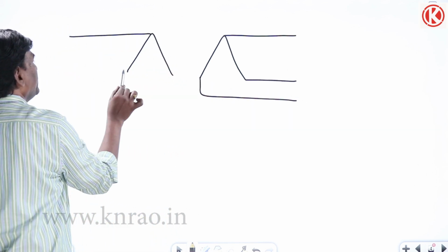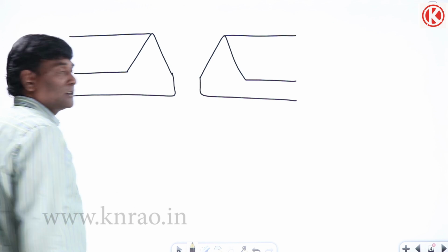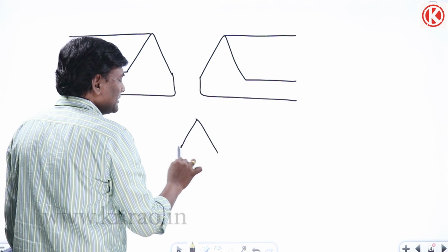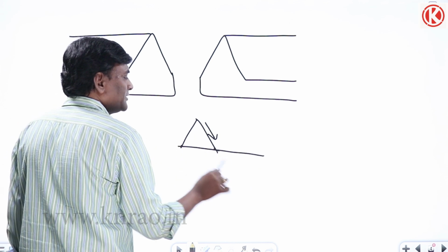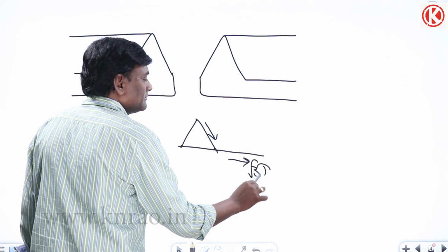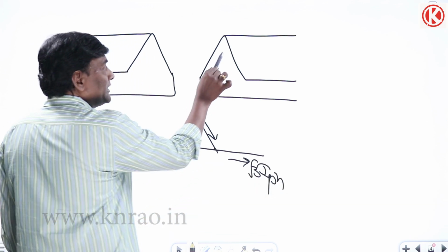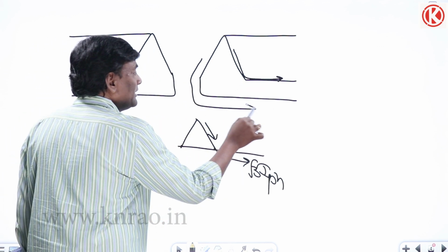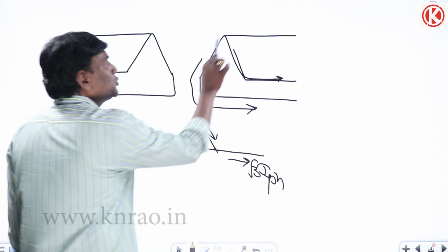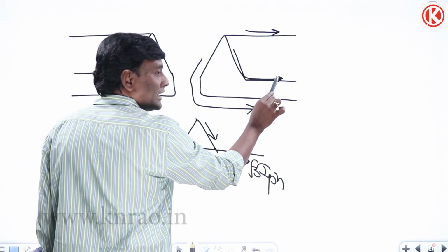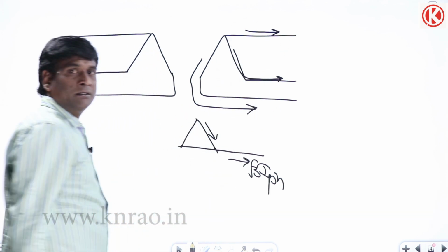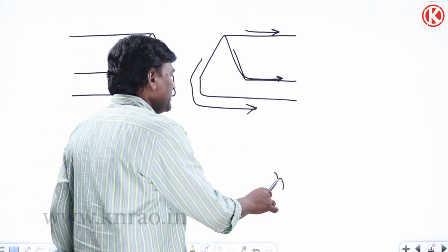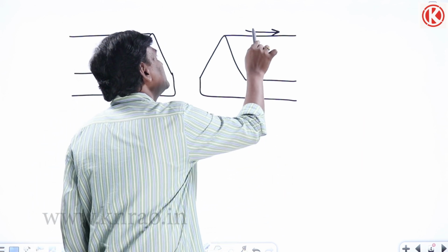many of the other people will focus on, see here this is phase current, because this is not there. If I have delta connection, if this is phase current, this is going to be root 3 times phase current. But if I think of here, I phase is going to be IL line current, and I phase is going to be IL line current, but nobody shows you here, because if this is IP, this is IP, how can this be IP? We should know, a bit of intricate analysis has to be done. Once you see this, you need not see it any other time.